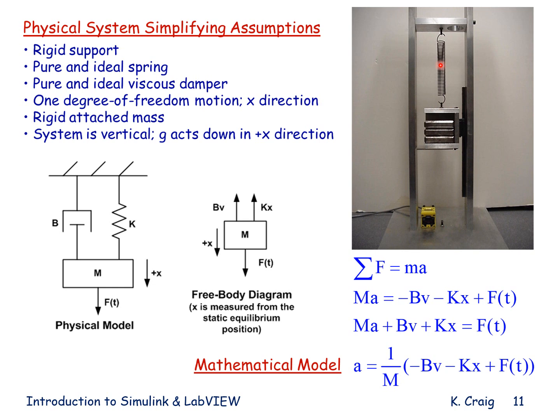Ideal means that it's linear in behavior. So although the spring has mass, I will neglect it. The spring dissipates energy, but I will neglect that. The spring is nonlinear if I stretch it too much, but I will treat it as being a linear spring, and I will stay within its linear range of operation.